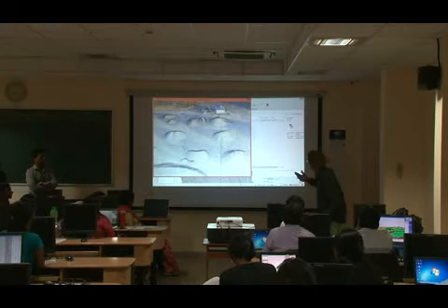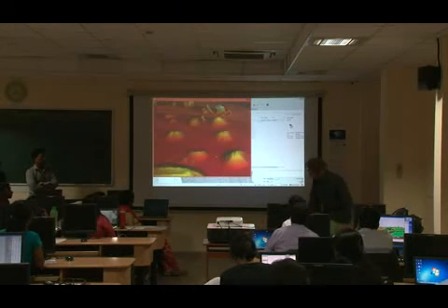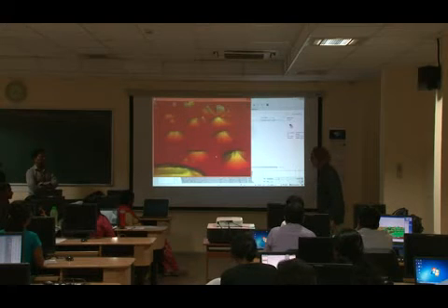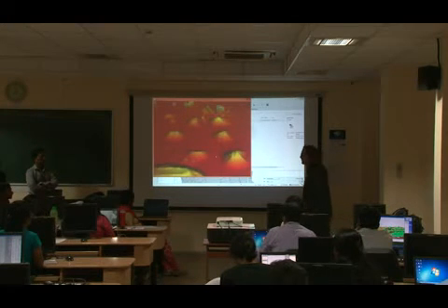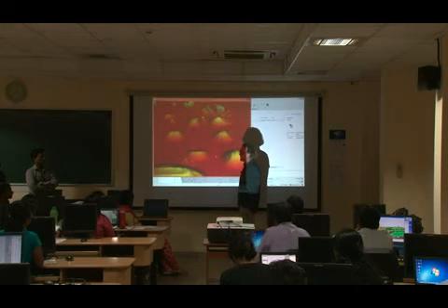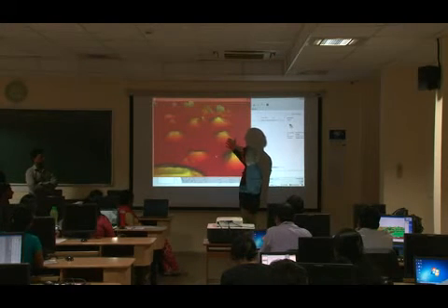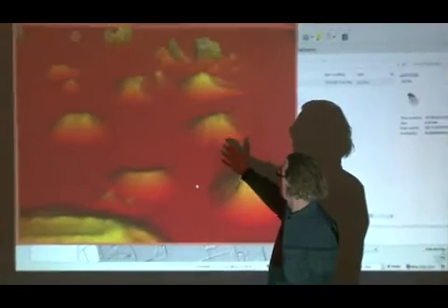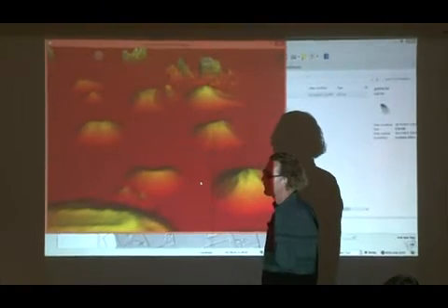Photogrammetry techniques, but it looks very similar to LiDAR. It's not exactly the same as LiDAR because it cannot penetrate vegetation. A typical scene where you would use this, for example, is places without vegetation.